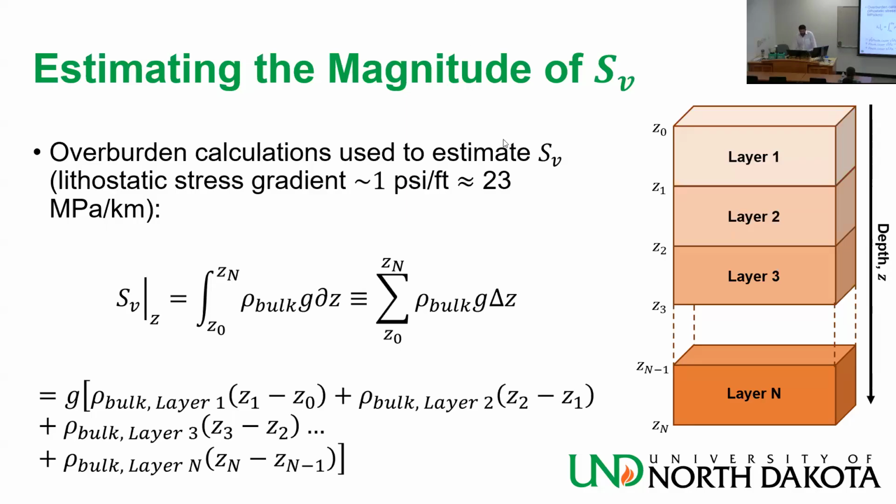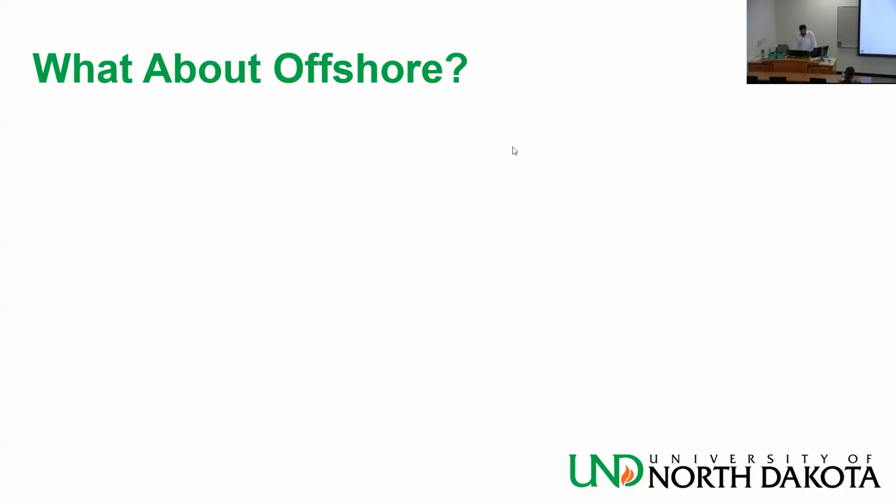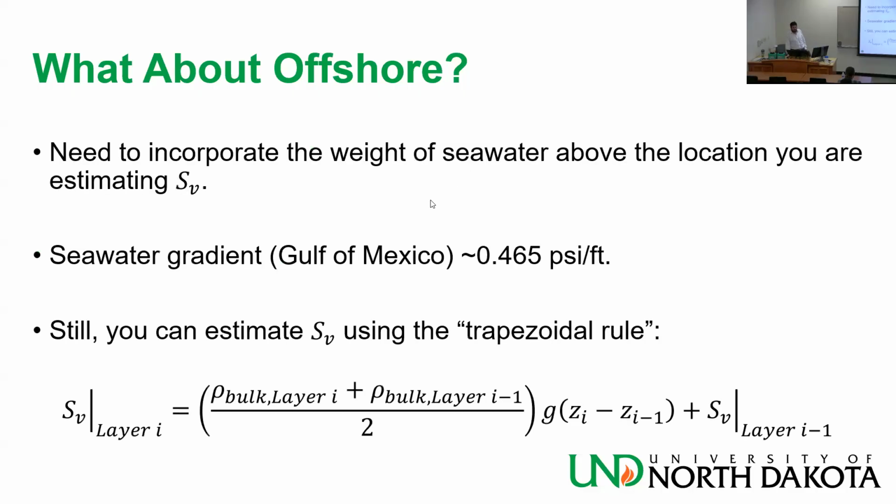What about if you are offshore? You have water on top, with a different density of water. Just remember, you only need to add the water depth on one of the layers. Don't do it on every layer, because then you are double counting.